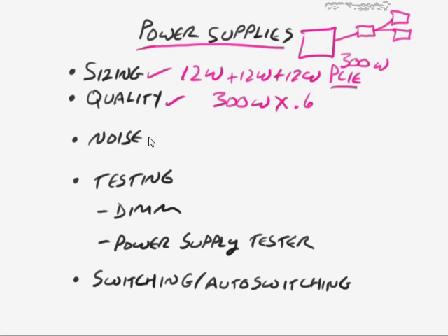Another thing you might want to consider for power supplies for yourself or for your customers is the noise that it makes. Now, it doesn't really bother me too much to have just normal power supply noise, but for some people it's highly annoying. So you might need to get a quieter model like the one I just showed you from PC Power and Cooling. Now, the other thing you might see is if the fans are going bad inside the power supply, sometimes they'll make a racket. Anytime that starts to happen, just replace the power supply.